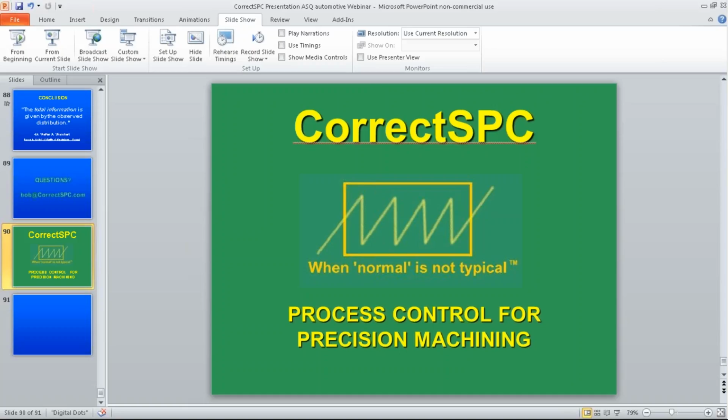You do it once. Because it's constant. You can look at it all you want, but it's a constant, so there's nothing to review. It's a totally different concept. It's controlling the variation, whereas in Shewhart, it's observing the variation. So they recalculate it to see if the observation has changed any. But here, there's no change. You're constantly adjusting between those two. So it's a constant. It's whatever you set it at. It's 133 if it's 75%. If you take a look at the calculation, it's a constant.